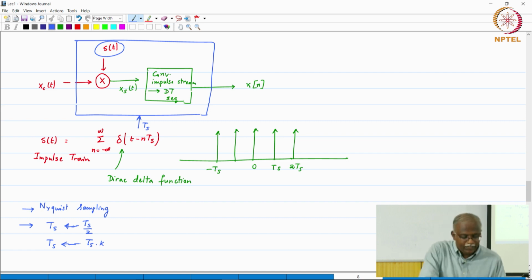So in a nutshell, multirate signal processing is about taking the foundation of DSP, where you are very familiar with the discrete time processing of a discrete time signal. For us, it is very important that we also be able to work with changing the sampling rate, keeping the underlying link to the continuous time signal, because if you change the sampling rate arbitrarily, you could run into impairments such as aliasing.